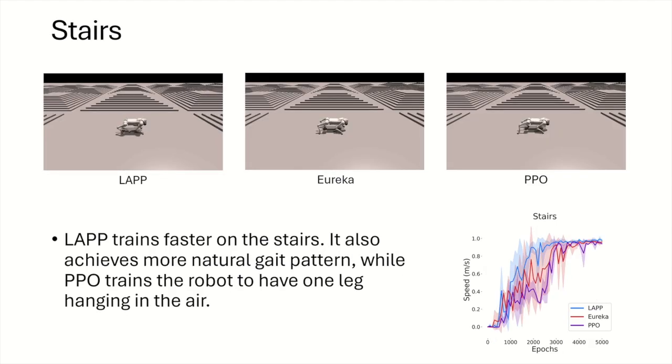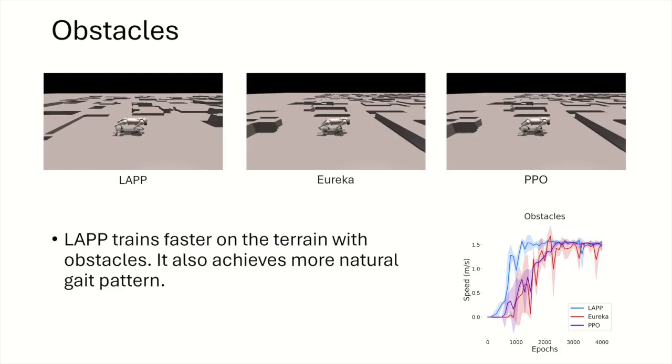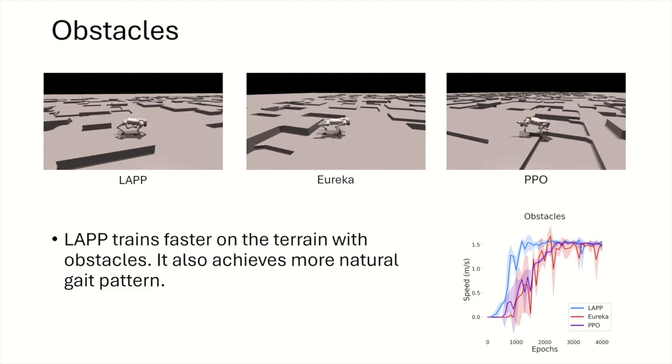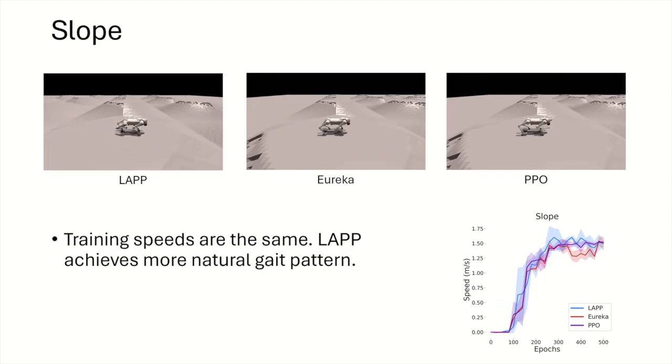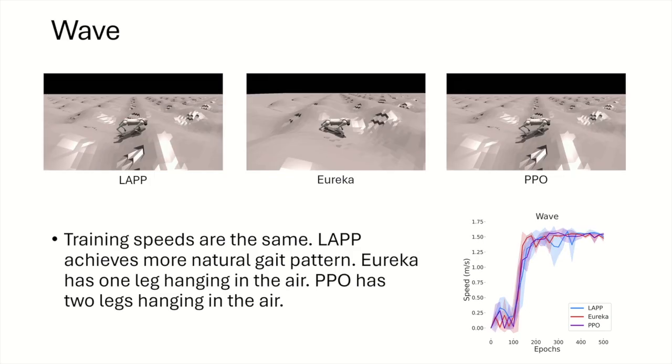Here, you can see LAPP applied to both quadruped locomotion and dexterous manipulation. In each case, the agent learns to perform increasingly complex and aligned behaviors, guided purely by language-based preference signals. Notably, LAPP enables impressive behaviors like a quadruped backflip, which are difficult or even impossible to train with standard reinforcement learning alone.